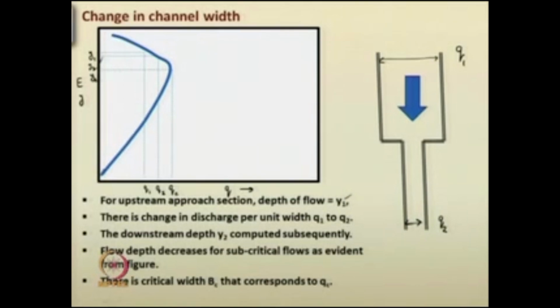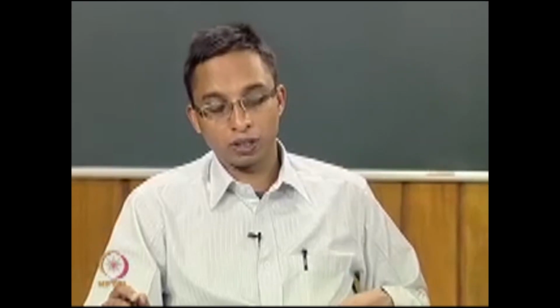So, what can you infer from this particular diagram? Actually, we have done it in our module 1 courses. For a given rectangular channel, the discharge will have its maximum when it is flowing in the critical state, that we have studied.